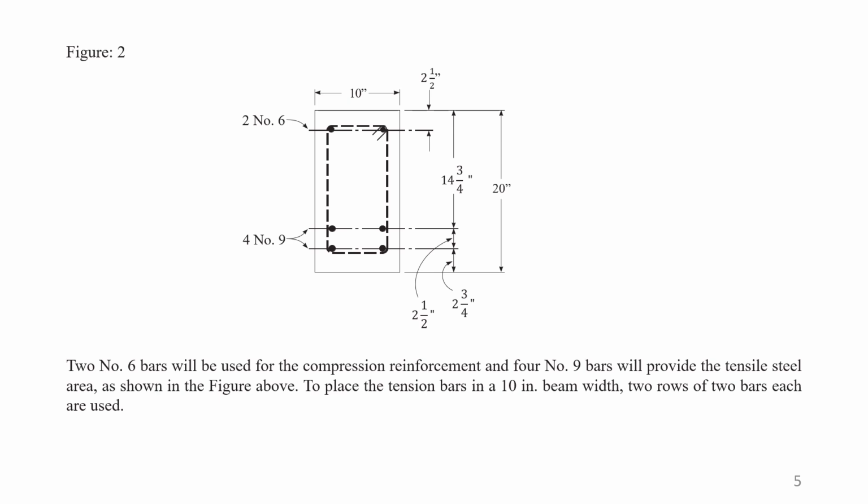Between these 2 layers of rod, there must be a spacer, which should not be less than 1 inch, or in most cases the bar size, which is easily available. Though from center to center it is 2.5 inches, half of each of the 2 rod diameters will be 1 rod, and the remaining space is for the spacer.